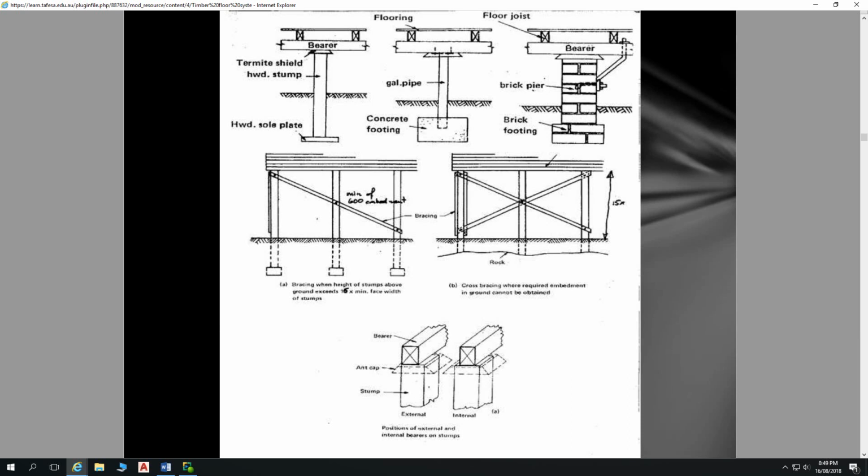I can't remember off the top of my head what Australian standard is used for specifying the tie-down of our concrete footing as per size. So there is an Australian standard for determining that. However, typically, once again, that's the preserve of engineers to work out what sort of wind loading there is happening on a building, how much concrete you need in that ground to hold it down.